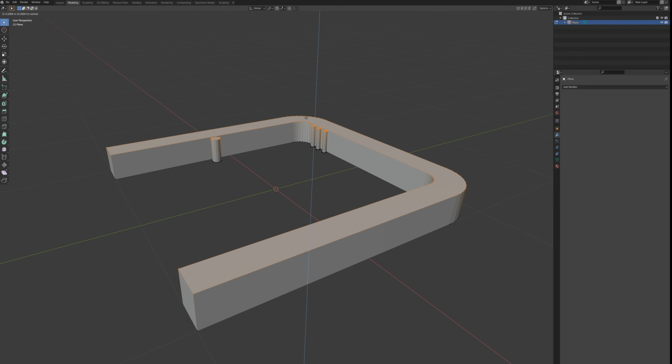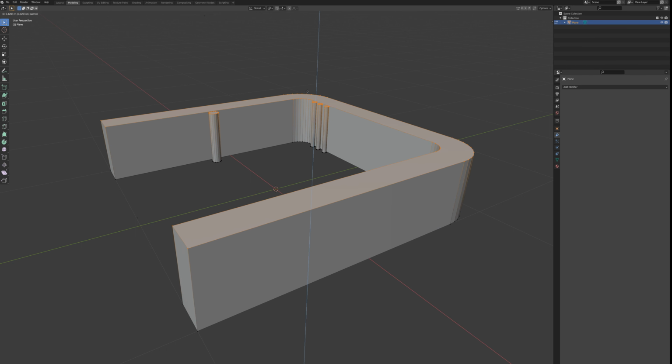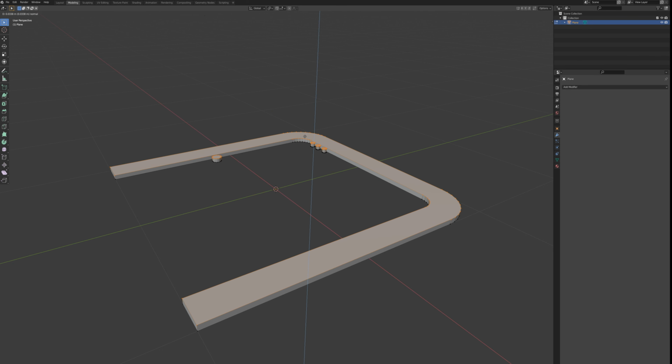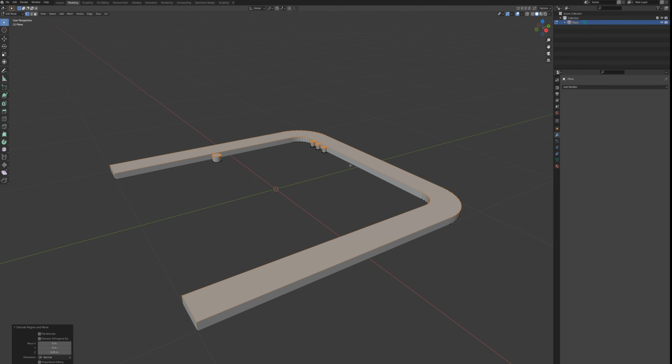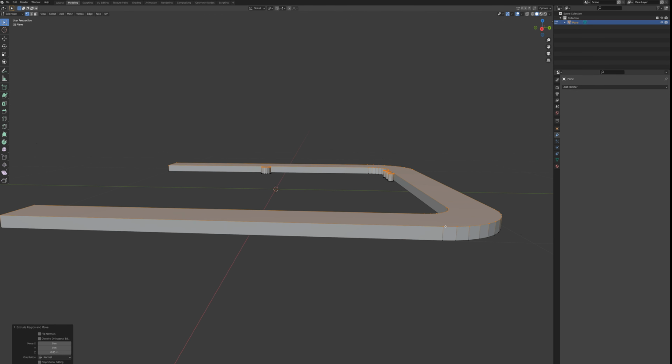So we're going to duplicate this initial section a whole bunch of times. So if you want a lower poly model, you make a bigger section here and make fewer duplicates. And for a higher poly model, it'll be a smaller cross section, lots of duplicates. So I'm going to type in 0.05, and that's the width I'm going to go with here.